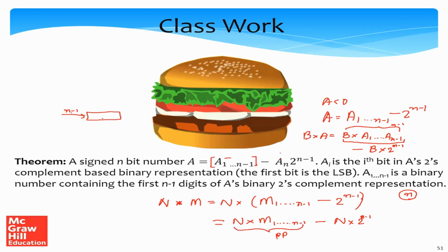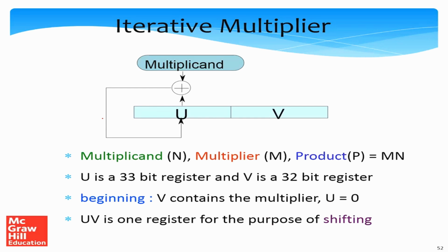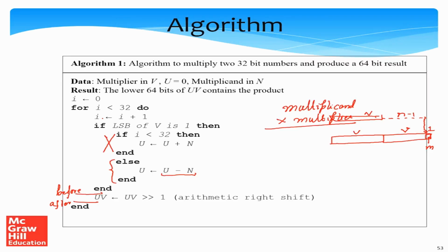We have been looking at different versions of the same idea, but the main reason that we do a right shift is basically to create a relative movement between the multiplicand and the partial product. Always the next partial sum should appear 1 bit left shifted as compared to the previous partial sum.